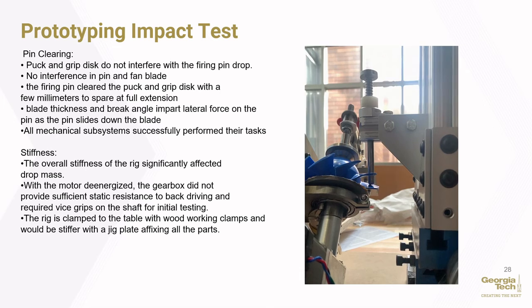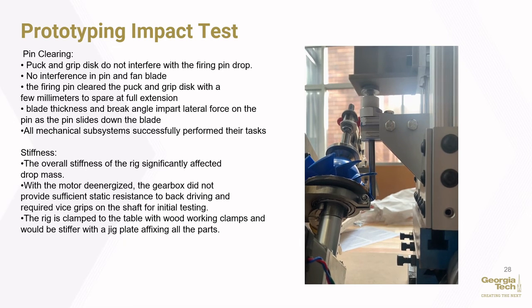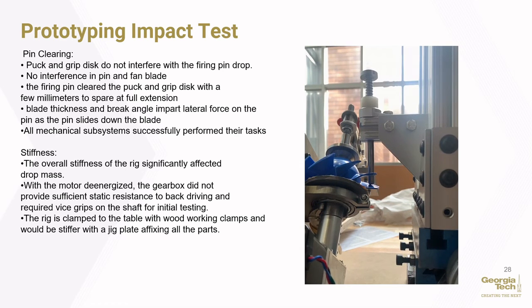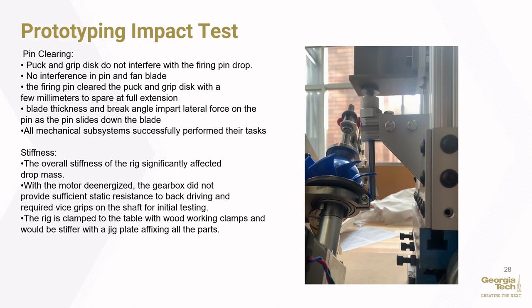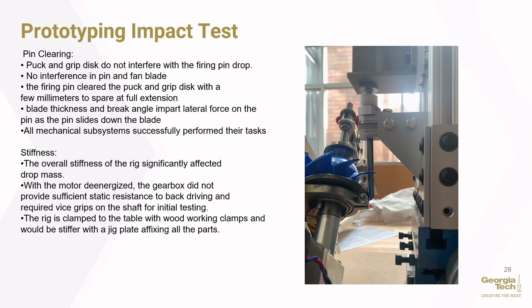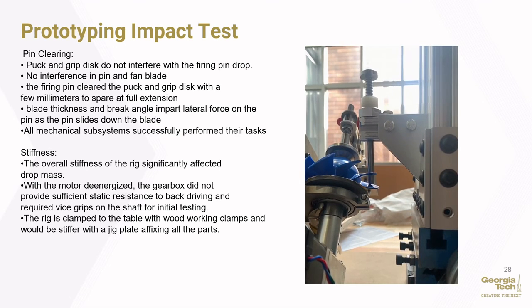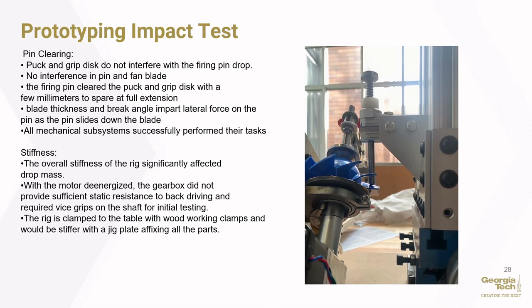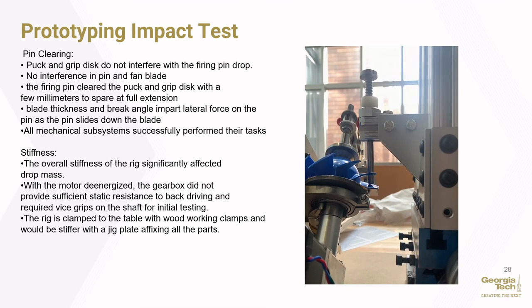After the physical prototype was machined and assembled, TTI asked us to ensure that the fixture could break through the fan blades. Here's a short slow-motion video of the impact of the mast cart on the firing pin, which caused the fan blade to snap at the root as expected. During the redesign of the fan grip from the underside, the new, larger grip plate slightly interferes with the fan blade as it breaks, which essentially creates a ramp that causes the firing pin to slide down at an angle.